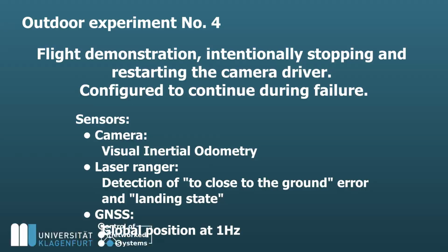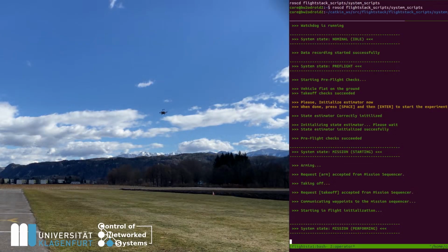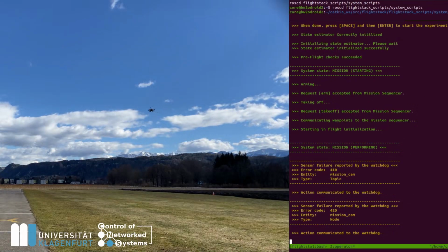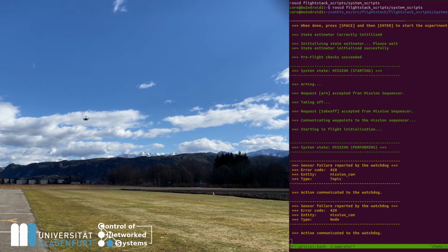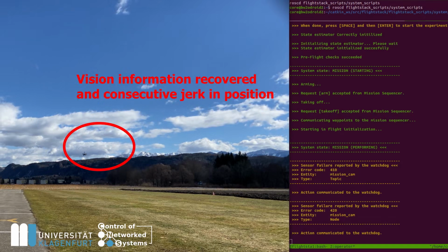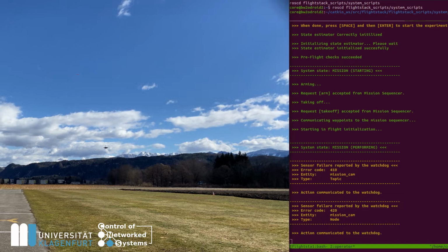To illustrate the benefit of this particular example, this flight shows how the vehicle behaves if the flight is continued after the image stream has stopped. The mission is started in the same way, but in this case, image failure is configured to not result in a hold state. This serves as an intentional example where persistent features that would be rediscovered in the scenery if the vehicle holds are not existent because the vehicle moved during the image loss.